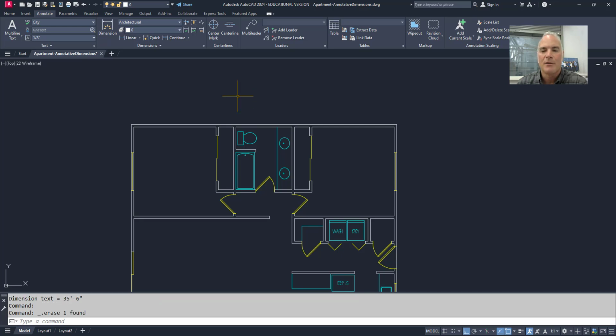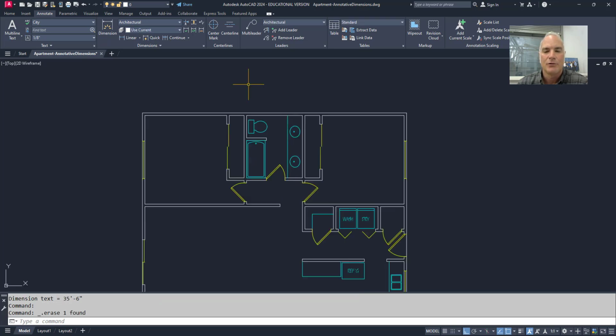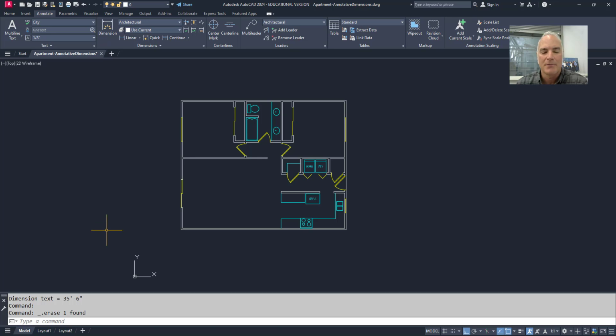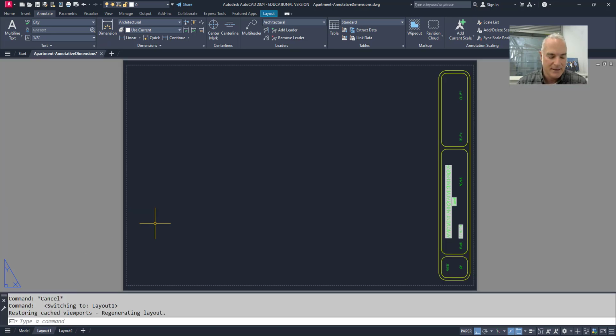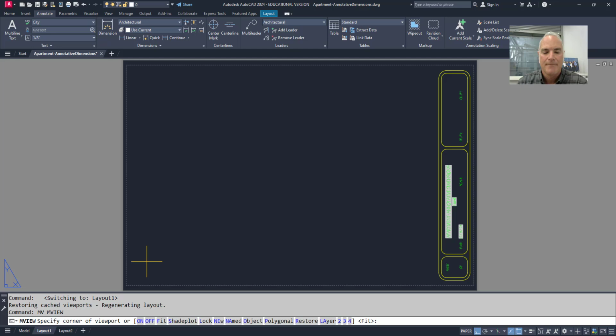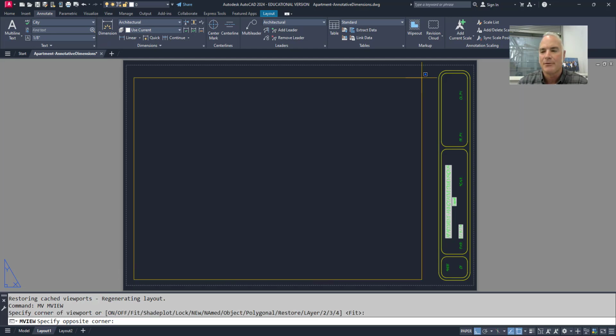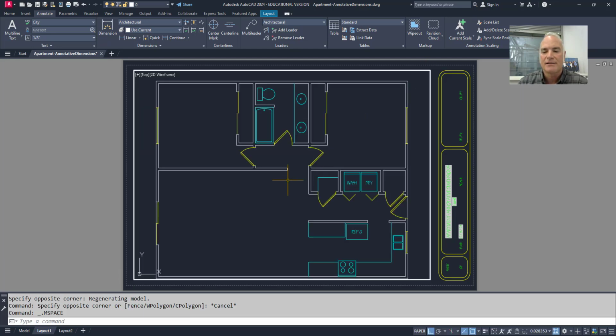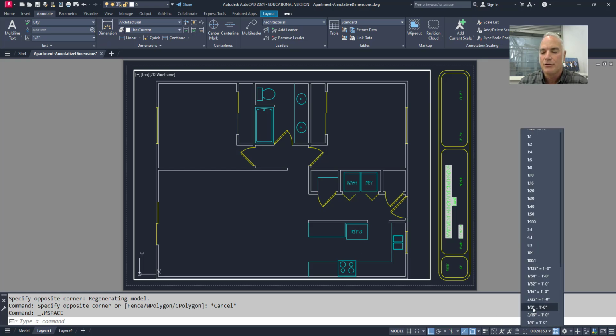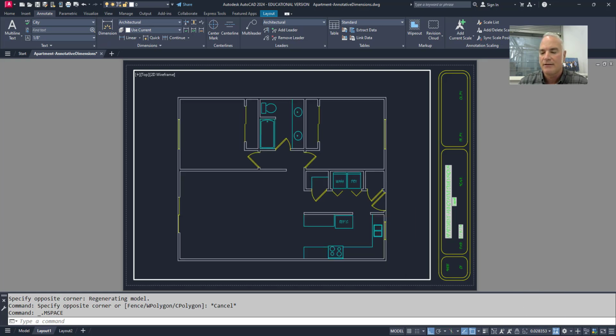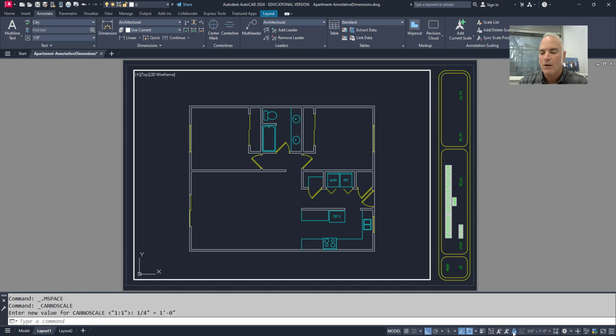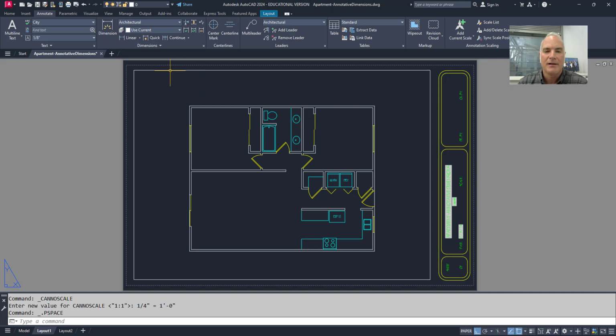And it's not going to appear to be correct when we get to model space or paper space. Now it actually works if I'm here in paper space and I create a viewport, for example, and then I adjust the scale of that viewport to 1/4 of an inch and lock it. When I place my dimension in paper space, it's going to appear to be the right size. So this is the way most people do it.